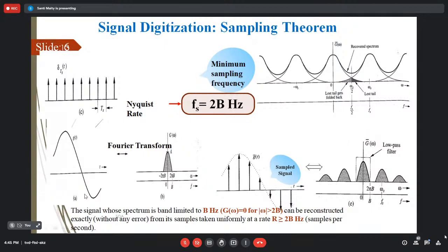So suppose you have a continuous time varying signal. It's an analog signal, and you would like to go for its digitization. I'm not talking about the amplitude discretization, which comes in the form of quantization in my talk. I'm just talking about the time discretization, which is called sampling. So this needs discretization, and how can it be done? I need to consider a function that's called a series of impulses or impulse train.